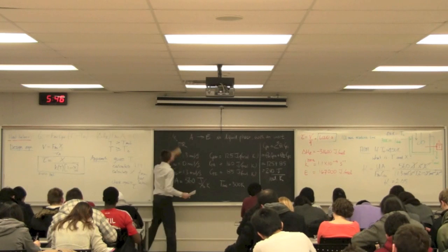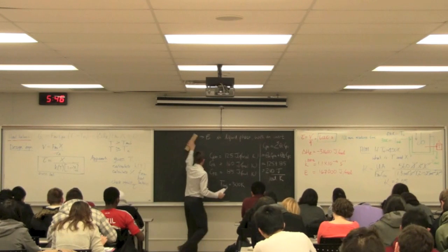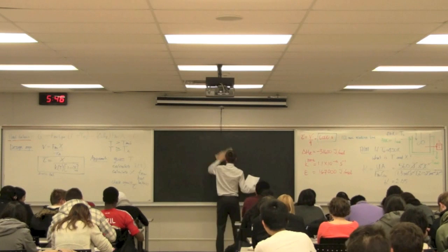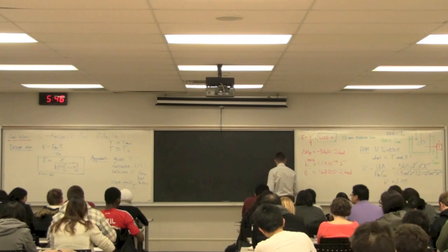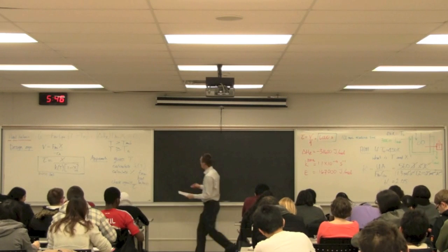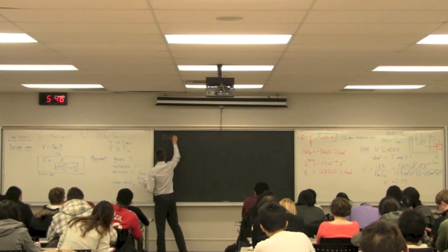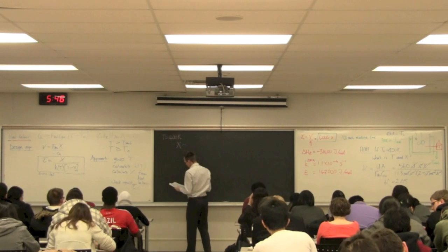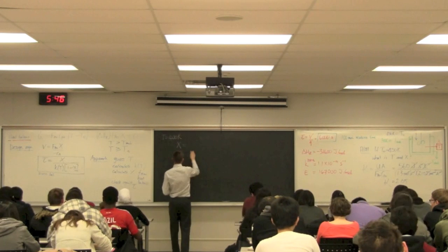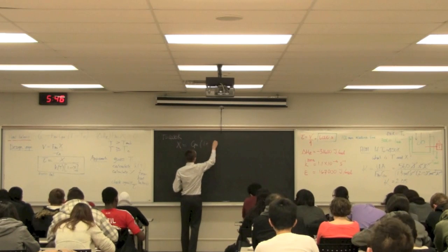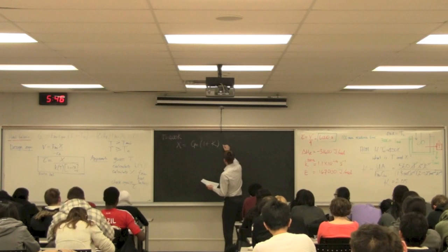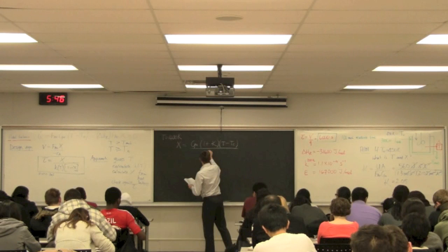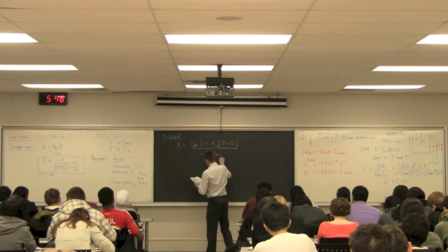So we did one iteration of that yesterday, where we ended off the class. And there were some questions afterwards, and people maybe want to go through this again. So I'll just step through our initial guess at 400 Kelvin. I said, well, let me estimate my conversion. My conversion X is given by Cp0 (1 plus kappa). So I just take that heat balance equation and rearrange for conversion: T minus Tc divided through by the negative heat of reaction.